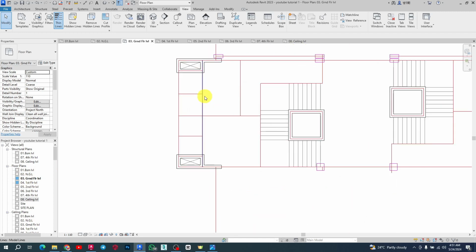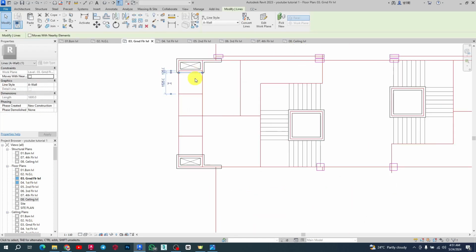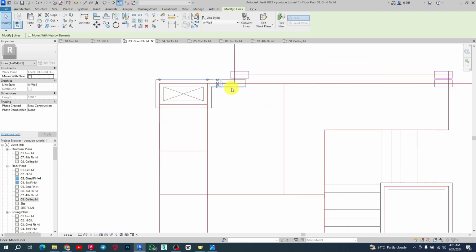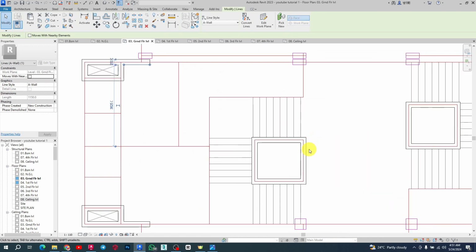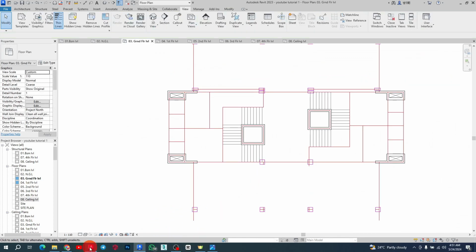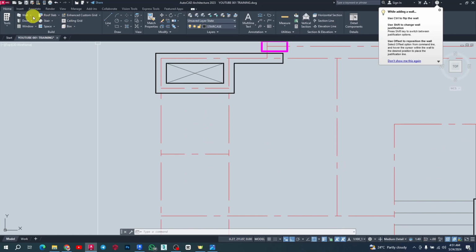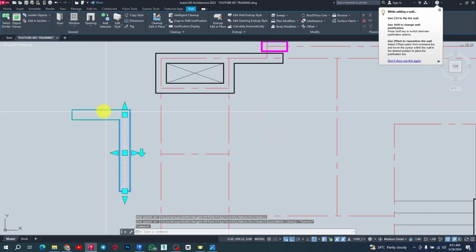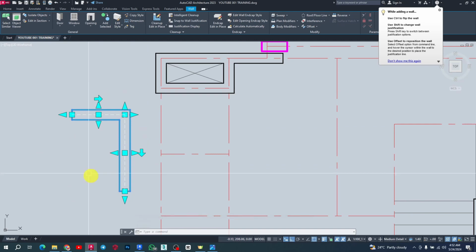To add to that, if you notice from the previous video, when we imported our drawing, we did not have the shear wall position. The shear wall was not highlighted on our drawing, and that is because in AutoCAD we used it as wall, so most of it was designed as wall. When you have walls, Revit will not be able to interpret the polygon, it will not be able to interpret what you're trying to achieve there. So always convert it to line work.